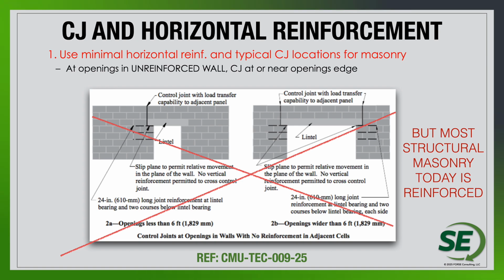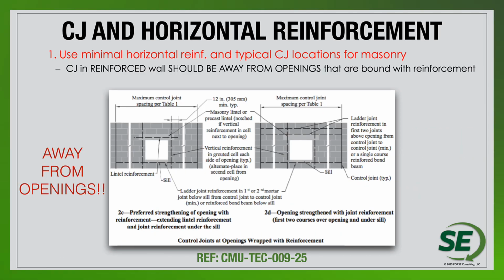Within those guides, again, we do look at diagrams like this where we can see that it's still recommended within the guide when we have an unreinforced wall, but obviously most of the walls that we're looking at today are going to be reinforced elements. And so making sure that once we have reinforced masonry elements, we look at control joints away from the openings, which would be very prudent. Similar diagram, but this time showing the reinforcement, showing that we have plenty of reinforcement to prevent any cracks from occurring at the corners. And so that's going to be a really nice design option.